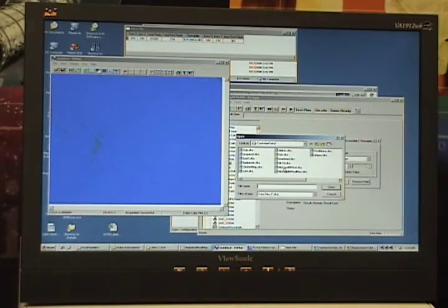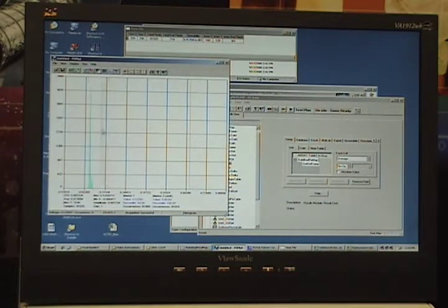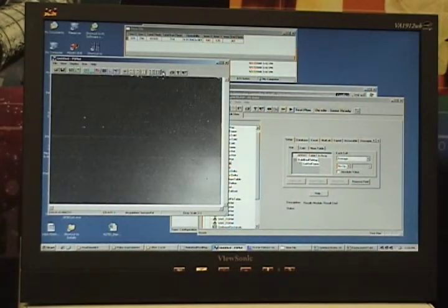Let's pull up the NETD map in PyPlot. Let's pull up a histogram view and increase the contrast. We can set the black point and the white point, then return to the grayscale plot and maximize the contrast. In this example, we were aligning the lens by hand, so you can see the result of some misalignment.